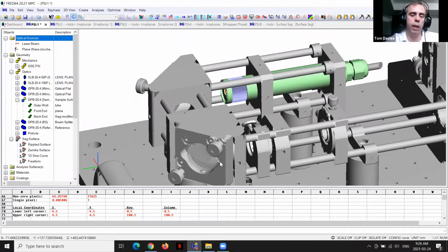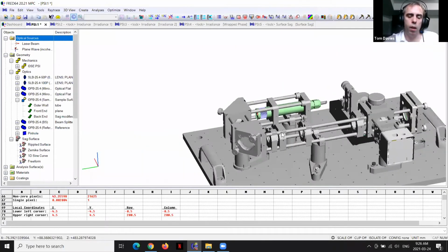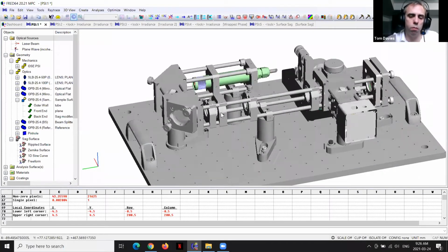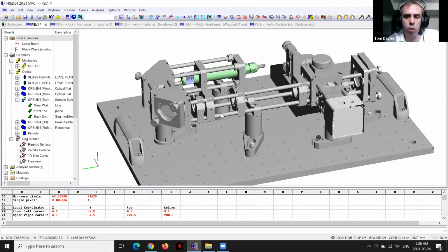If you needed to account for minor reflection components from the lenses or a small level of scatter from the mirrors, effects like that can also be handled by modifying the coatings put on the lenses and the scatter models that would be relevant for the mirrors or the lens surfaces themselves, basically simulating the small amount of scatter due to surface roughness from polished optics, for example.